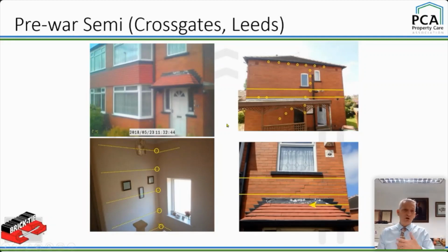We've got a bulging wall. We've got cracks at the junctions. This is the top of the landing. So that's needed lots of intervention. We've even had to heli-beam the central section to stiffen it across that void where the staircase is. And those little dots are just where the surveyors picked out for visual purposes where the lateral restraints are going.